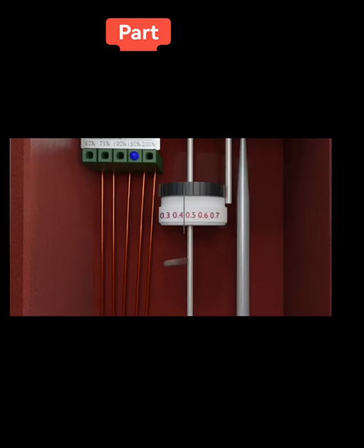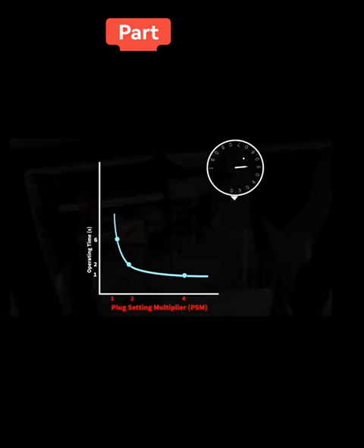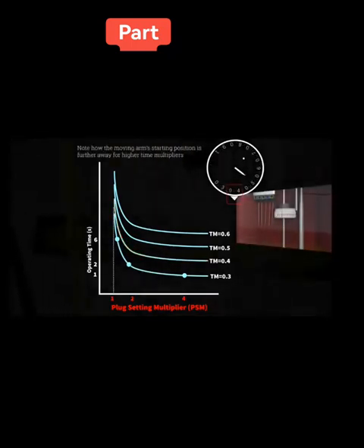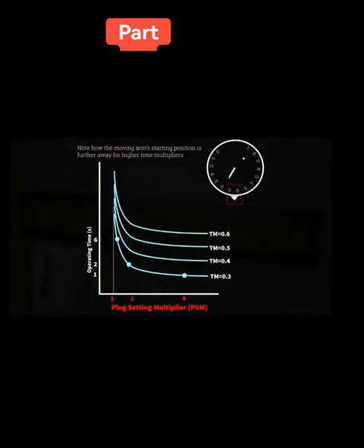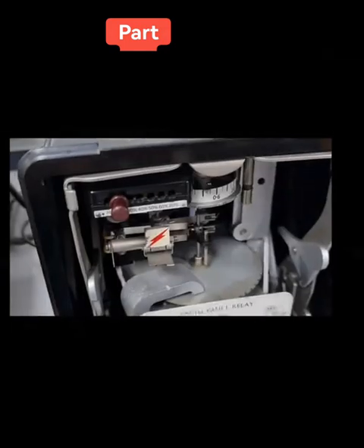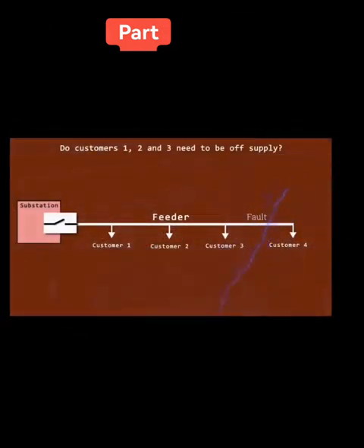So now what does this mean? The position of the plug determines how many turns couple into the magnetic core, which helps to induce the torque into the disc, right? So the higher the plug settings, the less sensitive the relay is to the current. In fact, the pickup current, that's the current necessary to make the disc move, should align according to your plug settings.